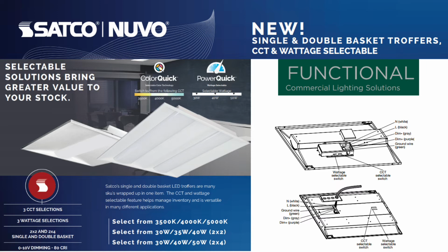So if you're doing a design with one of these fixtures, you need to select or decide which power you want, and then the design will be accurate. Because if you pick a 30 watt design and then decide, well, the customer really wants a 50, certainly you can do it and give them higher foot candle levels, but whatever you calculated for power would not be correct.